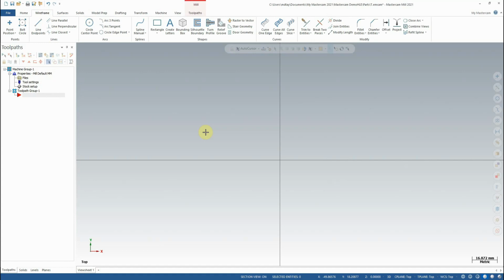What about tool selection? What tools are actually available in the shop where this is going to be produced? We may have access to the tool library in Mastercam, but does our shop actually have a 6-inch face mill? Maybe, maybe not. Do we have incremental imperial sized end mills by 32nds? Or by 16ths, or by 8ths? All these questions are good to consider to know what the most efficient tooling we can use is to machine features and still be realistic in our expectations here.